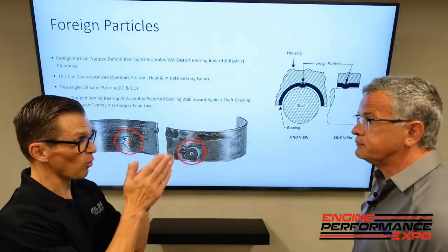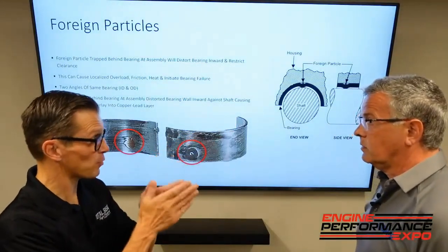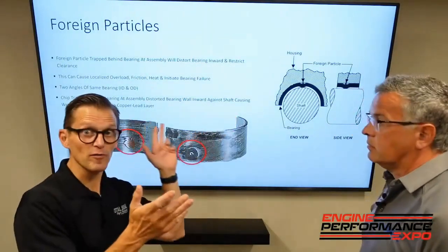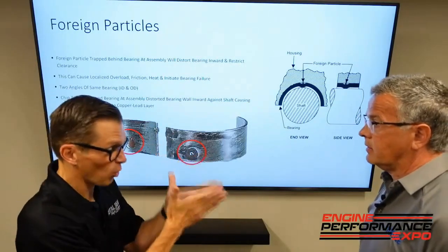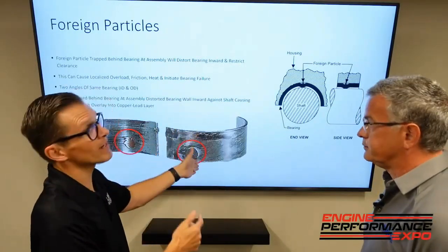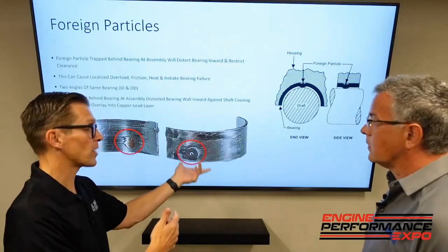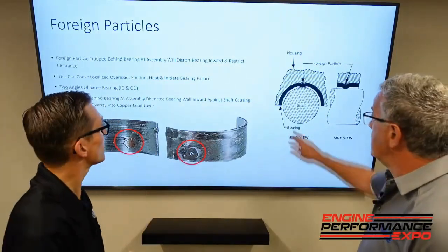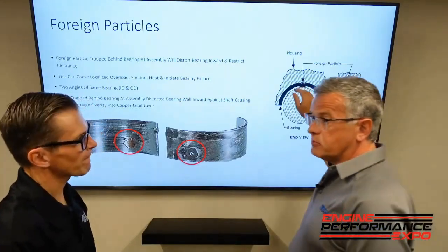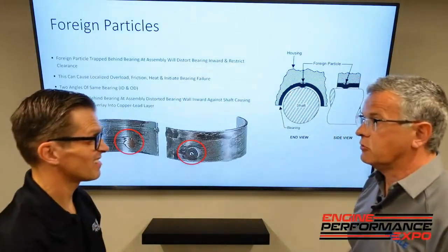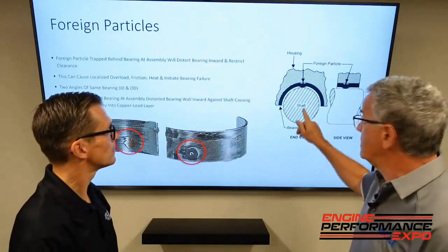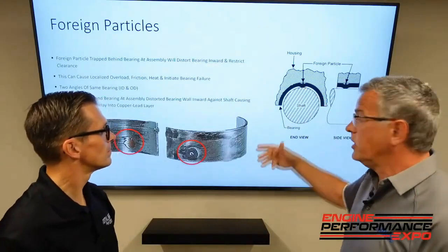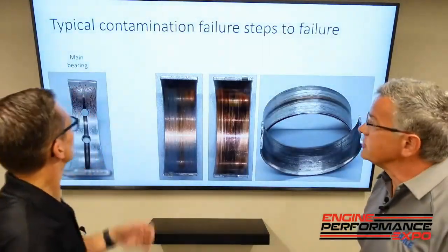Because those oil films get very, very thin under very high pressure, now we have an obstacle that can shorten that clearance even more. So it's going to have contact that begins to wear prematurely because it's non-uniform in distribution. In doing that, you're also creating frictional temperature. We're going to get into frictional temperatures again, but anytime debris is pushing in there, you can get some frictional temperatures.